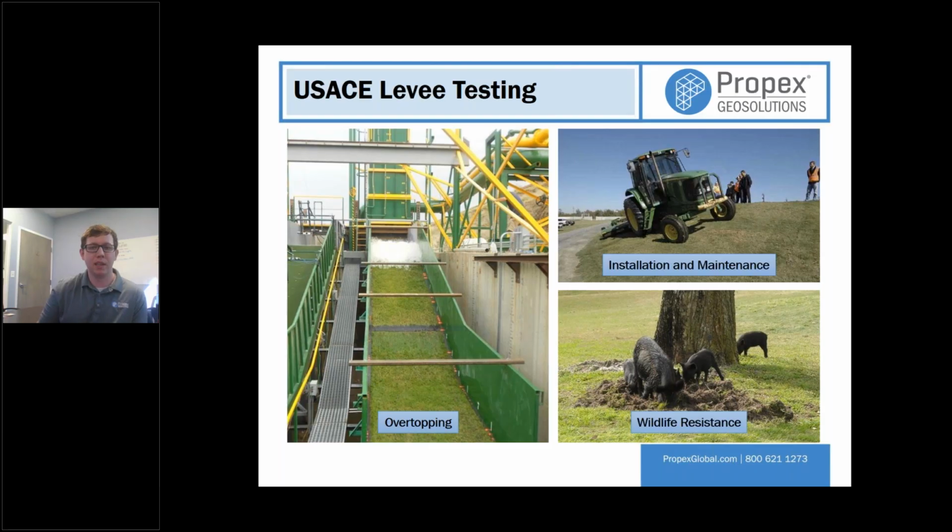They also did an installation and maintenance test. So they physically went out and installed the material with the same crew they use to maintain all the rest of their levees. They tried it to make sure that the strength of the material was enough to withstand the stresses of the tractors and the mowing equipment that they had to use on these levees from a normal application.